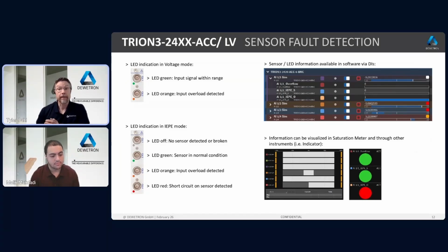So we talked about some of the changes or improvements we made to our chassis, with 3 of our chassis now going to the Generation 3 platform and utilizing PXI Express. So we talked about the speed increase and throughput there. We talked about the increased sample rates that we have with some of our cards, along with that increased resolution you get with the improved ADCs. So going from that 16 to that 24 bit gives you over 250x resolution inside your data and information that's coming into your system.